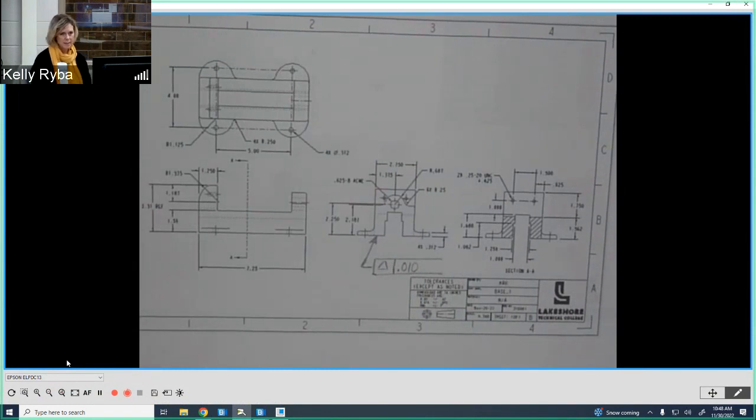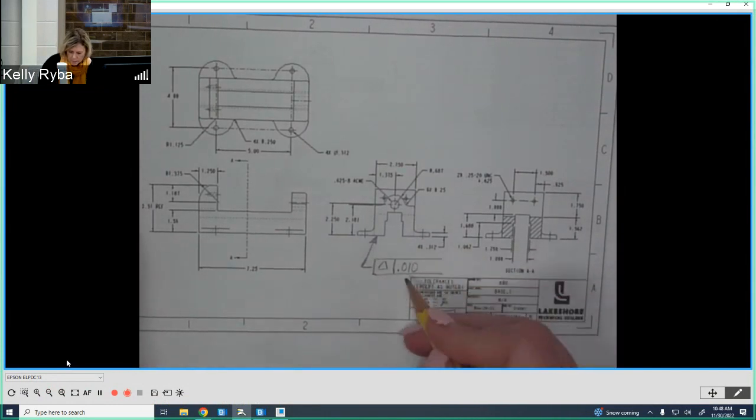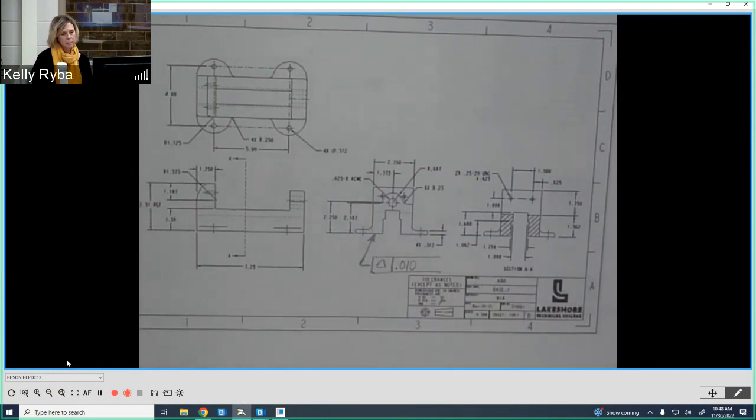This is a vise. It's not something that's super duper critical, right? So if we make it super duper flat, you're also going to take more time to make that flat, or flat and on the same surface, coplanar. But you're also then going to induce time and money. So we want to be reasonable. And so this would be flatness or surface profile of 10 thousandths.